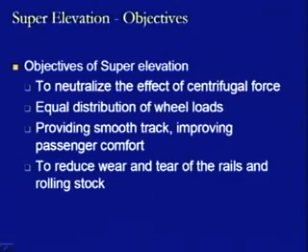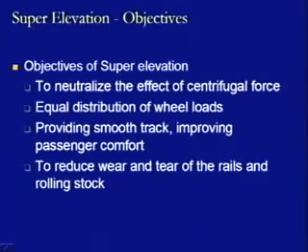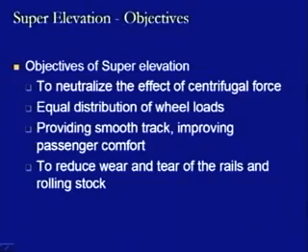Further, because of the non-provision of super elevation, where the centrifugal force is acting in the outward direction, because of the movement of the overall rolling stock in the outward direction or because of its rigidity, the relative movement of the front wheels and the trailing wheels means there are all chances of wear and tear taking place at a higher level.